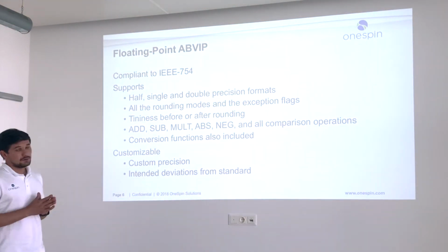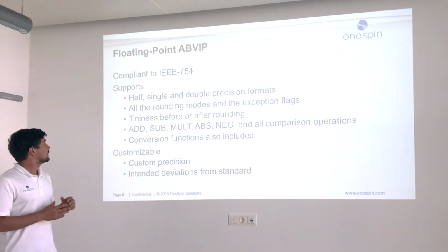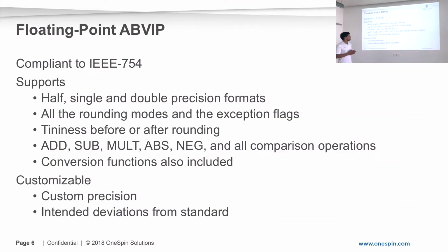As I mentioned before, it's compliant with the standard. It supports half, single, and double precision formats, all the rounding modes and the exception flags, tininess before or after rounding, addition, subtraction, multiplication, absolute value, negation, and all comparison operations.